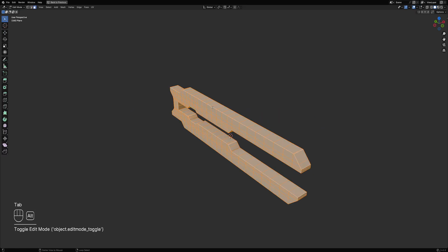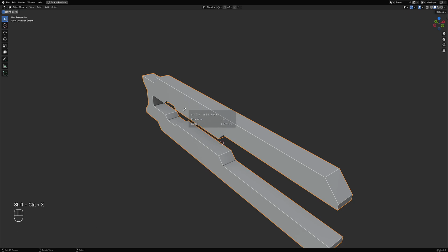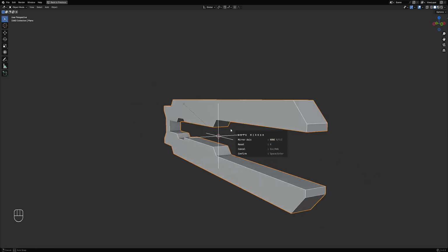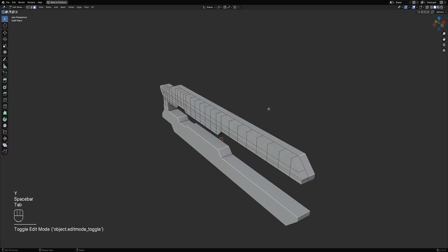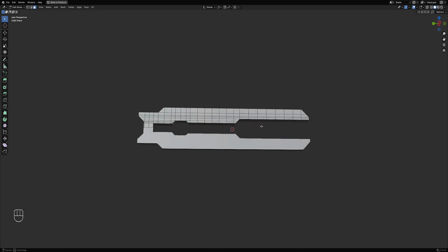This also applies the mirror, so we can reestablish it using auto mirror. Click on the geometry that you want as the real geometry. In this case, this one here. And this points to the origin point of the object. You'll then use the X; the axis colors up when you activate it, X, and then Z. We don't need Y because we don't need to mirror this to this. We got this. So now you're ready for randomization because you have all quads.